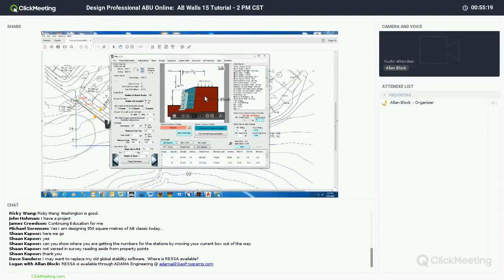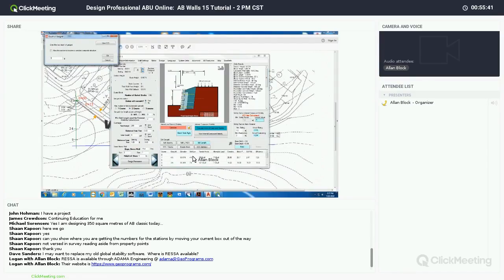grid. Now, based off of best practices, if you have a slope, a surcharge, or even seismic, they want to extend that top layer of grid. So what I'm going to do is lengthen that top layer of grid by hitting the Edit Lengths button, again above the spreadsheet, and click on the course of grid I want to edit. So I'm going to hit the course 4 with a 4 foot, and I'm going to match it to the one before. That's just another constructability standpoint, less grid numbers, less chance of a contractor messing up.